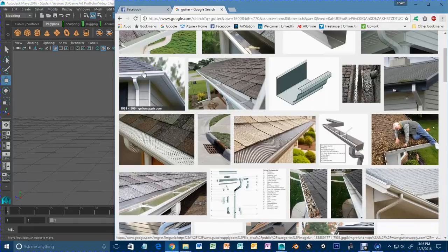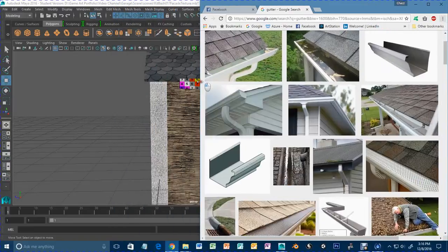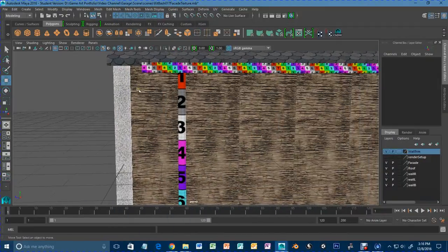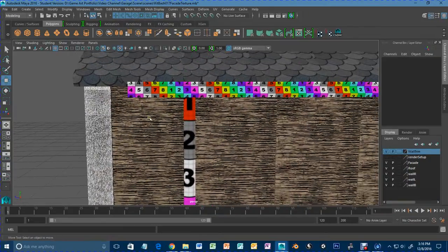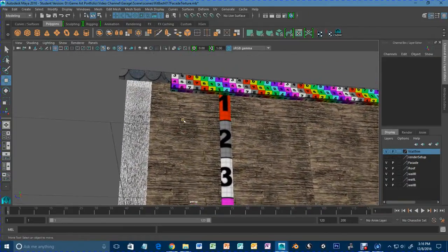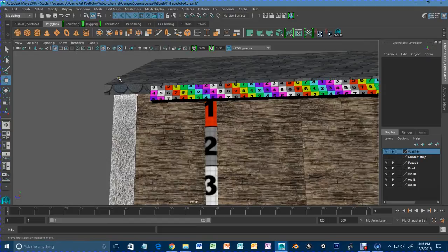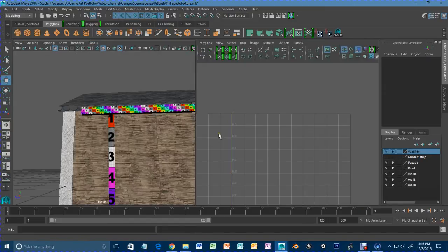And so this is actually kind of a fun trick that I like to use. So I'll show you a nice little trick here. What we're gonna do is we're actually gonna create a line, and then we're gonna extrude a rectangle along the line. And it's pretty sweet. It's a pretty sweet tool to use.